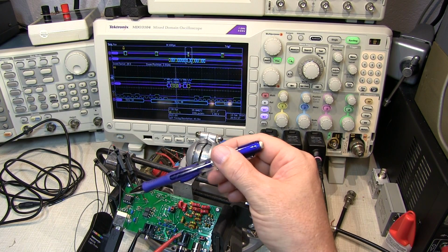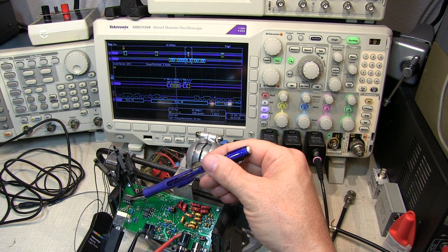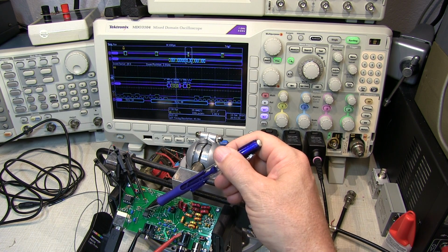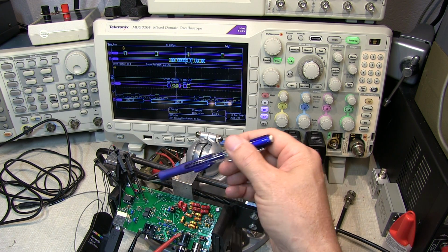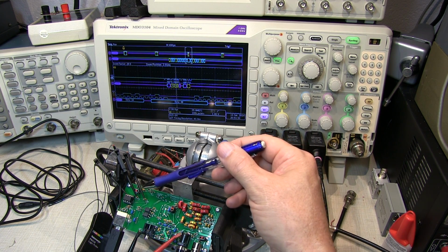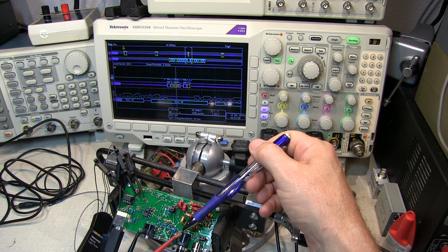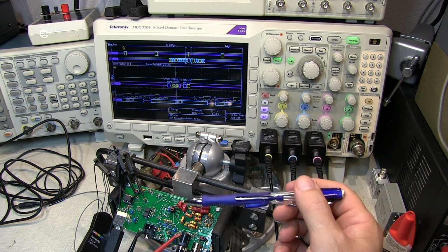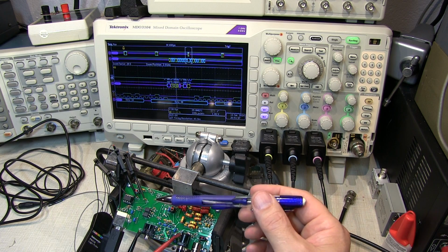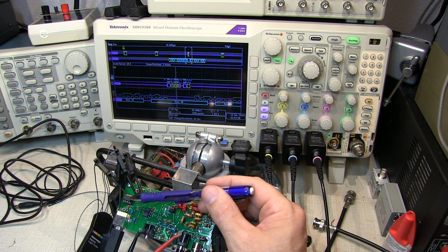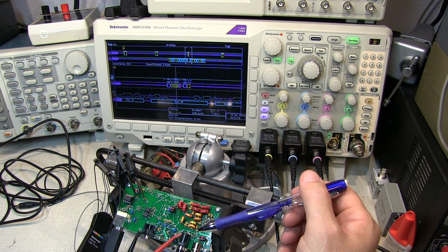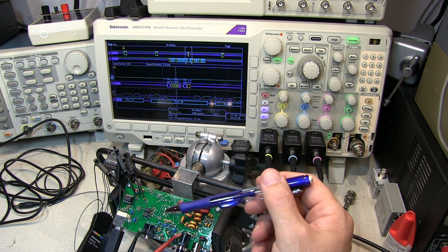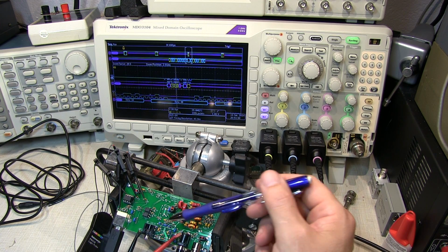Okay, here on the board, this is the microcontroller here. These are those two optocouplers right here, and this is the RF transformer that takes the output from the Si570, which is on the back side of the board, and brings it over into the rest of the analog receiver. Now the way this board is set up is that just about all of the integrated circuits, with the exception of the microcontroller, are surface mount devices that are on the back of the board.